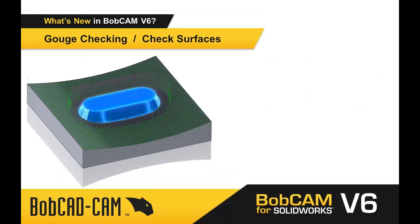The second one that we want to talk about here is Gouge Check with CheckSurfaces. Have you ever been frustrated trying to create toolpath that only cuts in specific areas of your model? Or are you trying to avoid cutting into walls, pre-machined or already finished features, or even work holding? In BobCAM V6, gouge checking provides another level of containment for your 3D toolpaths. Using gouge checking, you can check against single or multiple surfaces.